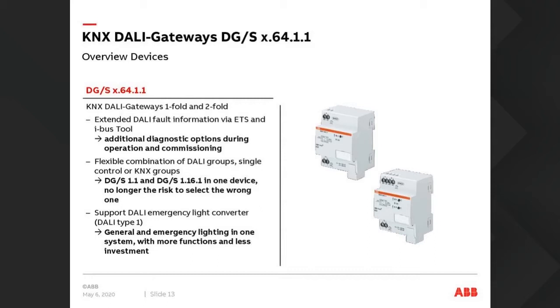We also support the emergency lighting converter, the DALI Type 1 emergency lighting converter. I'll show you that as well. I have one connected up here. And it really makes this device quite useful. This is one of the main selling points I have for it, that we can use it to control standard DALI lights, which we do all over the place, and we can also use it for the emergency light system.